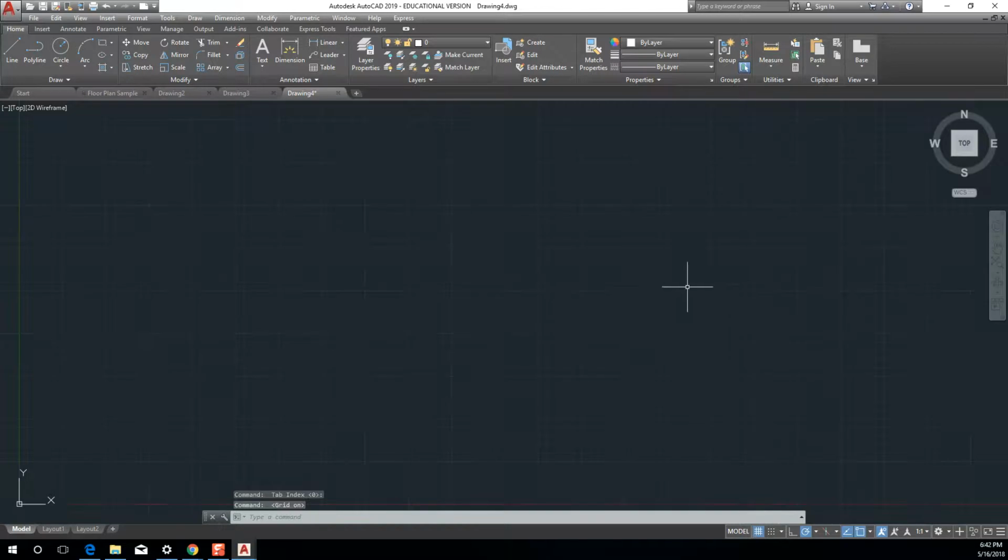Oh, and I just turned it off. Let me turn it back on. Okay. Now, the problem with this grid, though, is that you think, hey, there's a grid in AutoCAD. That's great. I'll use it to snap to it and measure things or draw according to it, right? But it doesn't really work that way very well. It's not something that you really interact with. In AutoCAD, it's more of a visual indication, more so than something that you interact with and use to help you draw. Okay, so usually when I draw in AutoCAD, I actually turn it off so that visually I just can't see it, because I somewhat feel like if there's a grid there, I should be able to use it a little bit more than you actually do in AutoCAD. And if I can't really use it, I just kind of turn it off, honestly.